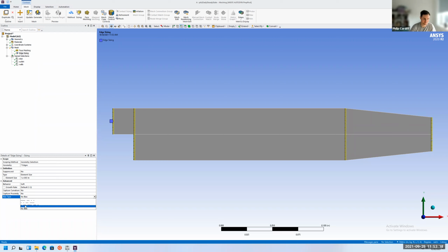That might sound a bit confusing, but if I select this one that has a little dash, and then picks up a bigger dash, and then the biggest dash in the center, and then smaller again, that middle one is going to put small elements or cells near both ends of each edge, and then larger ones in the center. So that will better capture the boundary layer. To define the factor, let's set it to 5. This is the ratio of the biggest to the smallest. You can see here, you now have very small elements or cells near the wall, and then larger ones in the center.